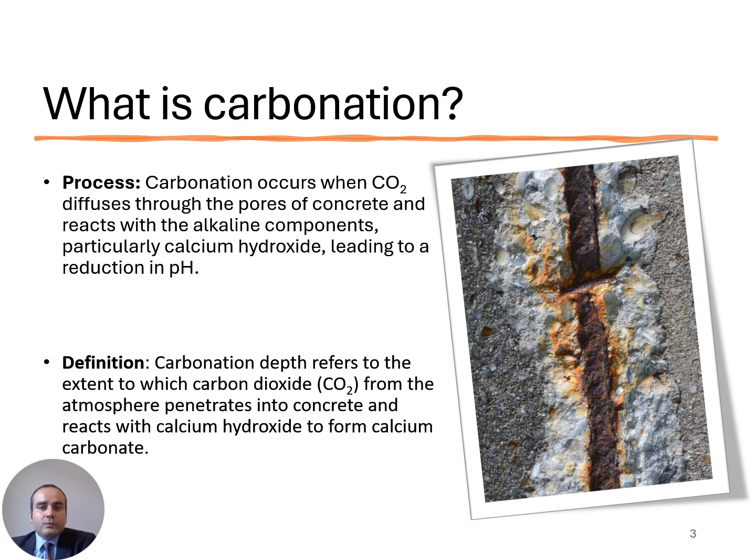The depth to which carbonation penetrates the concrete is referred to as the carbonation depth. This depth is influenced by several factors, including the concrete's porosity, moisture content, and the surrounding CO2 concentration.